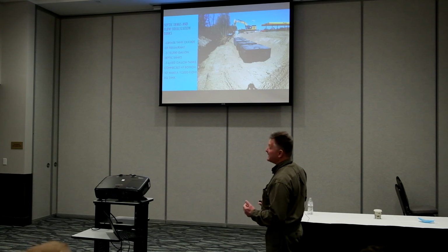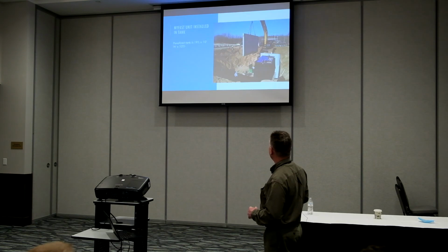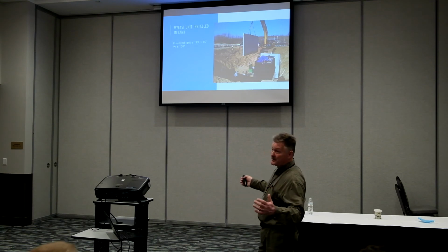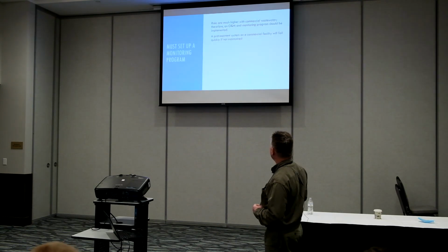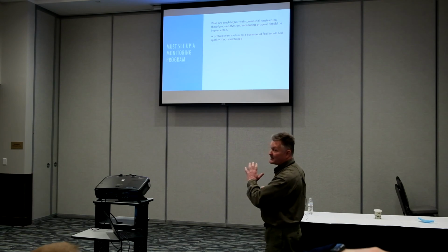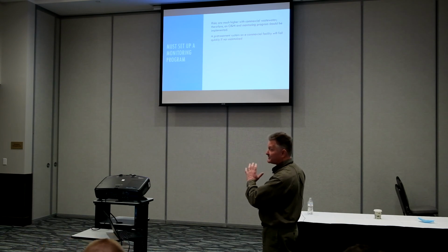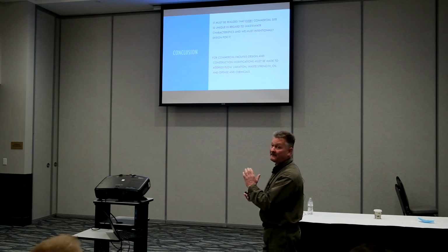That's the tanks going in. So three 10,000 gallon tanks and basically 12,000 gallons of flow equalization. Equalize out that flow. Here's one of the aeration units going in. A lot of these bigger tanks, we have to go into either cast-in-place or panelized tanks. And here's a picture of the system. So any of those systems, we need to make sure they don't go in the ground unless we have some kind of monitoring program. Very high strength or very risky. If the system's not maintained, it will go belly up very quick.